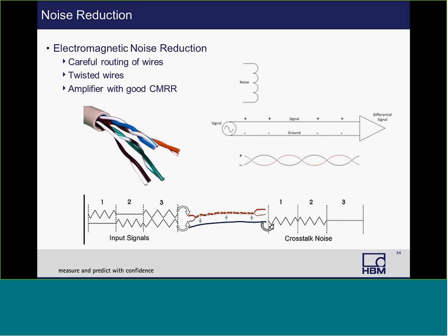And you see here examples of twisted pair wires. When signals are sent down twisted pair wires, when one wire in the pair becomes positive and the other wire becomes negative by the same amount, any of the wires near this pair will be affected by the crosstalk, and if the sum is zero, then the effects of the crosstalk will be eliminated. So it's important we have equal length wires.